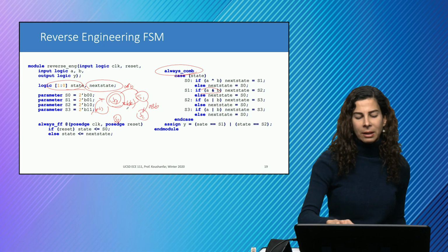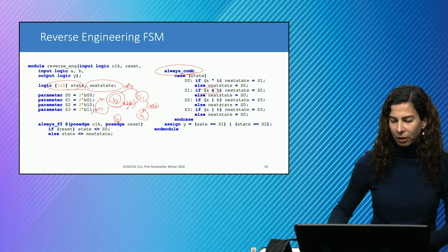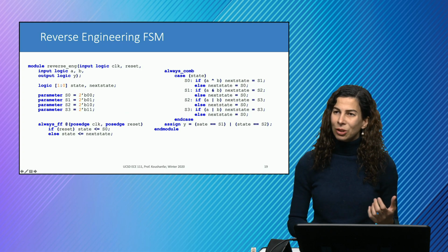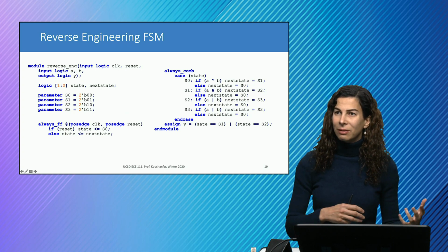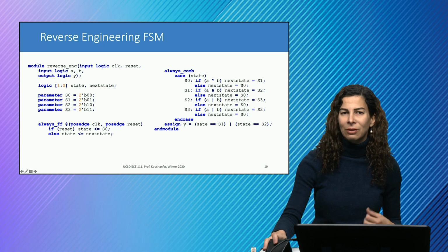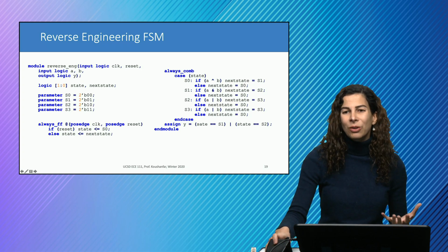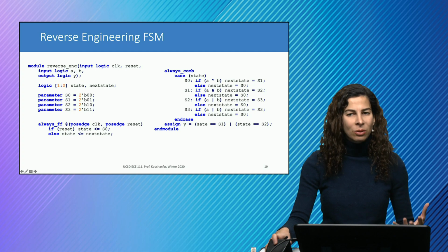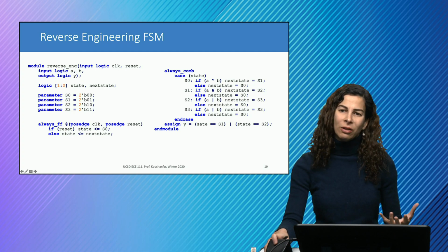And then Y is some kind of logic of this. So if you have written a good standardized finite state machine, you could always go back and do this calculation in reverse. And people who see your code would be able to understand what you have been trying to do and what your state transition graph was implying.